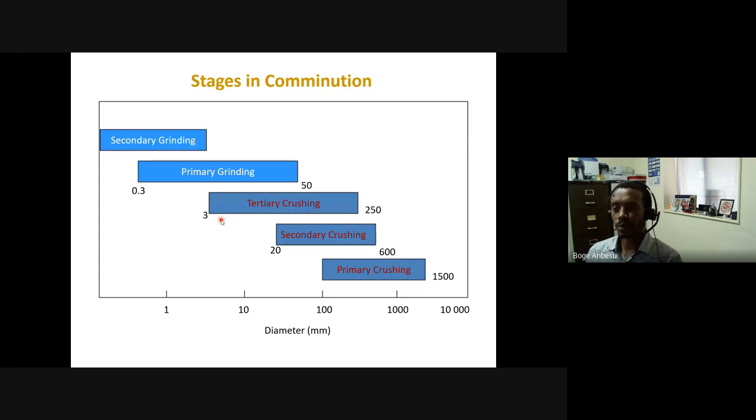That's why we produce only a small number of rocks, but those rocks are relatively large in size. But with impact, we apply a very high stress to the rocks. That's why we're shattering the rock into many pieces. So once you do that, usually you produce a different size distribution. As I said, you produce fine, coarse, and intermediate particles, and those are wide in particle size.